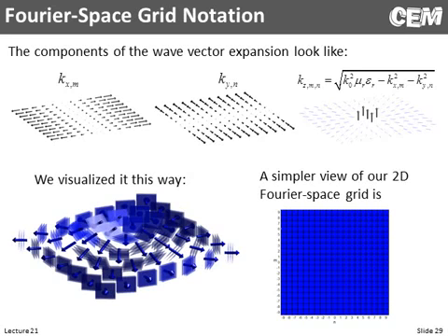But notice now, in the x direction, we have 19 spatial harmonics, and up and down 19 spatial harmonics. But think about the diagonal. In this direction, we actually have more than 19 spatial harmonics. It's 19 times the square root of 2 or something like that. So we actually have better resolution along the diagonal. But is that really buying us anything if we don't have the resolution along the vertical or horizontal axes? I would argue no, and I would argue the spatial harmonics off in these corners are a bit of a waste. In fact, we could drop them without reducing our accuracy really at all.